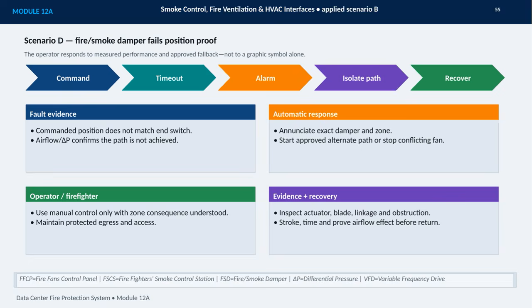Recovery is not complete after the actuator moves. I inspect the actuator, blades, linkage, and any obstruction, then stroke and time the damper, and prove the resulting airflow effect before returning it to service. Measured performance, not the symbol alone, is the basis for action.